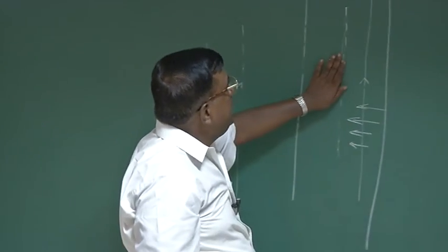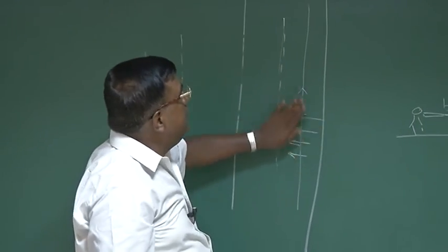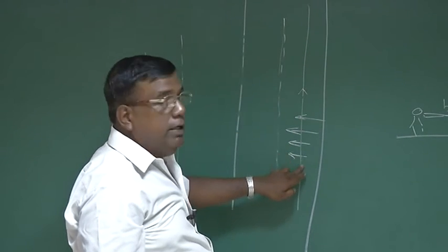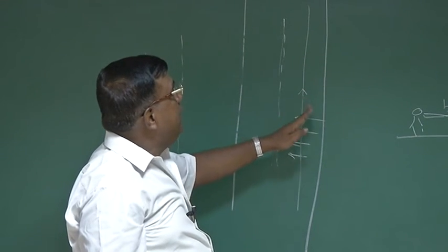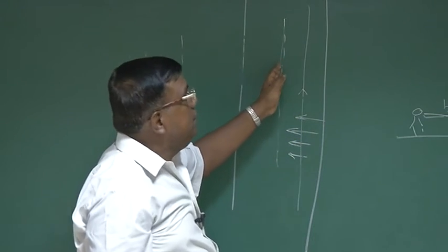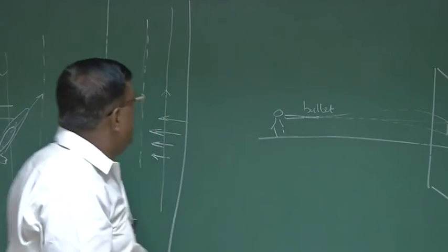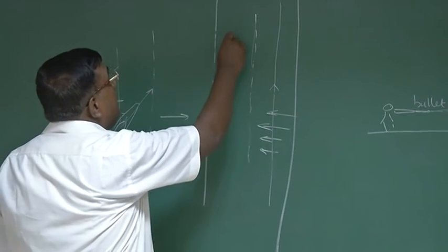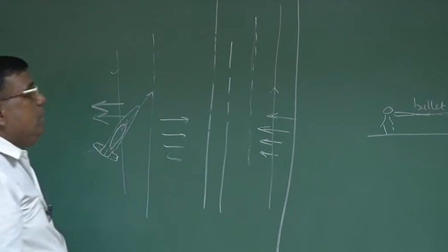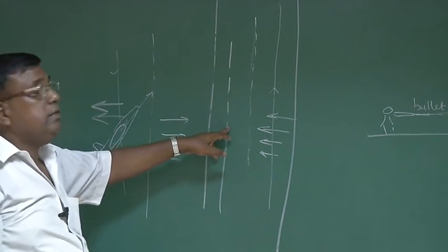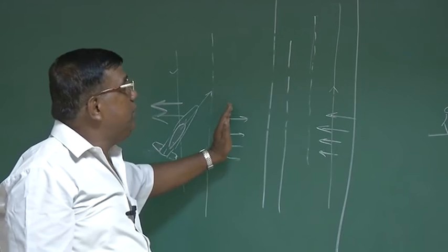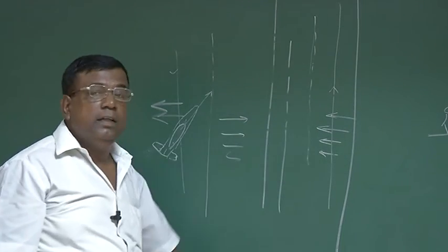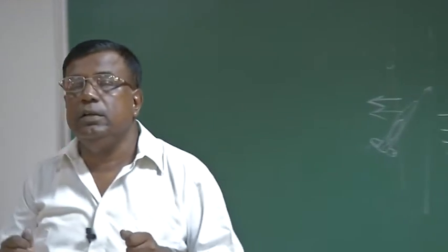So what is that way? If I want to land here, if I know wind is coming from the right hand side, I will be aiming at some other point here, another line here, knowing very well I will be drifted anyway back to this, like the example I have given here. Similarly, if wind is coming from this side, I will create an imaginary line here. My approach, I will try to approach this as the central line where I am going to land. Because of this wind, I will automatically get drifted. I will come near the central line. So the pilot with his visual aid, if they are not flying through an instrument landing system, will be applying corrections.